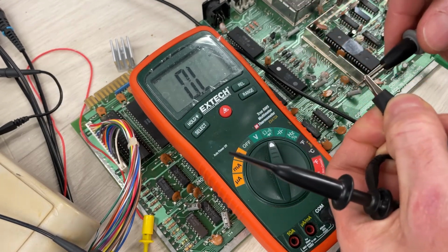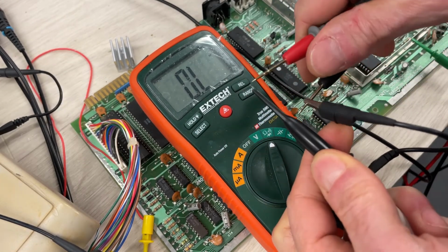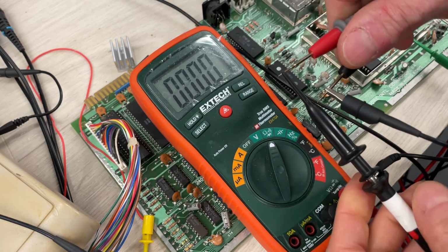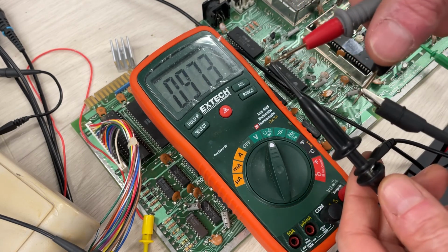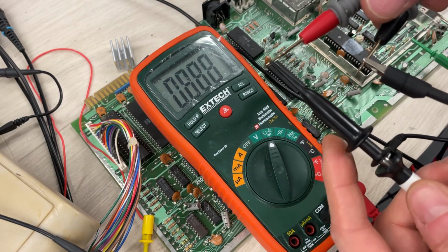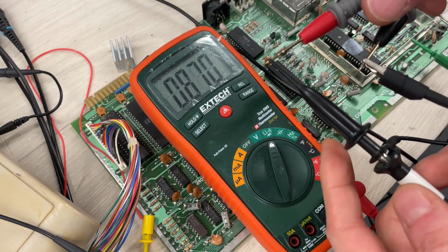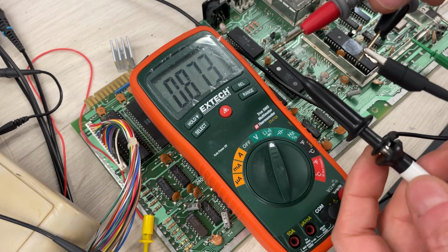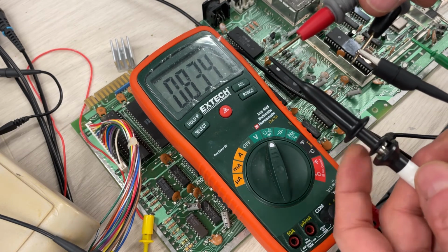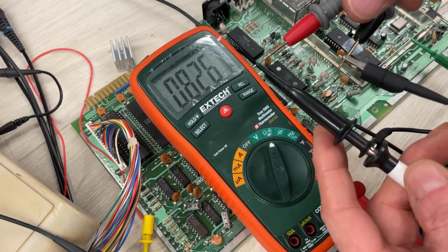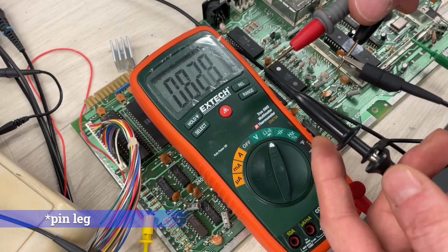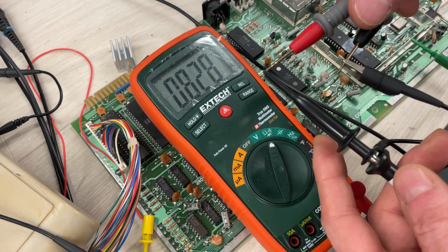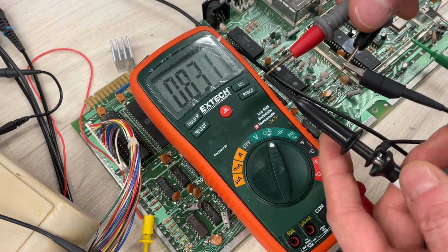And I basically found that the probe is showing about 1 kilo ohm between ground and the probing tip. Basically, when I'm probing with this probe, I'm adding a 1 kilo ohm resistance to ground to the probed pin. So I guess maybe I'm pulling down the line?